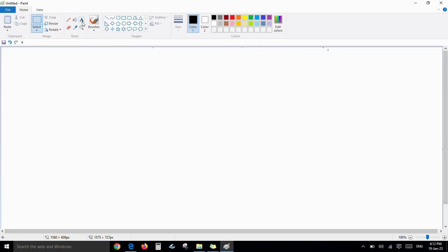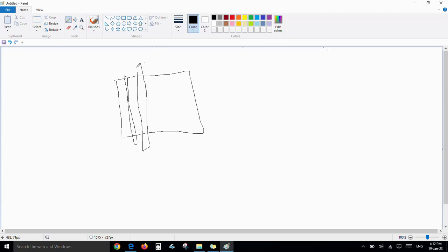Well proximity effect is like if I had one MOSFET at the end of the channel, right? I will be having the poly here, active and all those things, no? So whenever, while doing the fabrication, if it is the end of my block, there will be a cutting process happening, there will be charge accumulation, and this will be damaging the poly here.